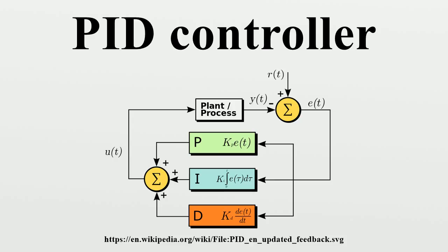Applying too much impetus when the error is small and is reducing will lead to overshoot. After overshooting, if the controller were to apply a large correction in the opposite direction and repeatedly overshoot the desired position, the output would oscillate around the set point in either a constant, growing, or decaying sinusoid. If the amplitude of the oscillations increase with time, the system is unstable. If they decrease, the system is stable. If the oscillations remain at a constant magnitude, the system is marginally stable.